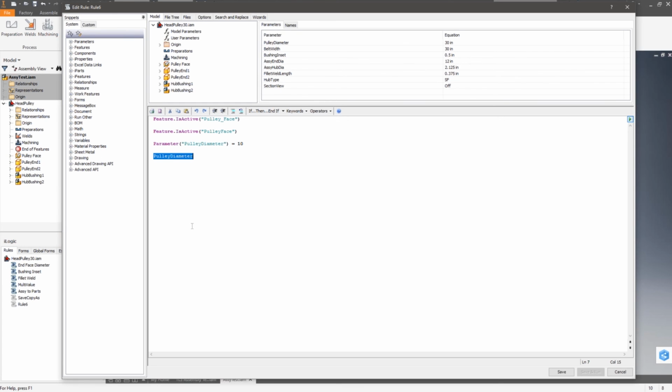If I have an assembly with 20 parts and multiple sub-assemblies with parts, pack and go is definitely the feature that you want to use, because it will grab everything. It looks at those file references and grabs everything in one shot. iLogic, we're not doing that. Well, you can do a pack and go if you want to create static subassemblies.